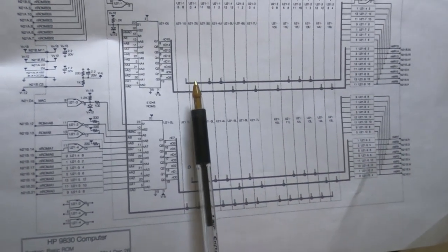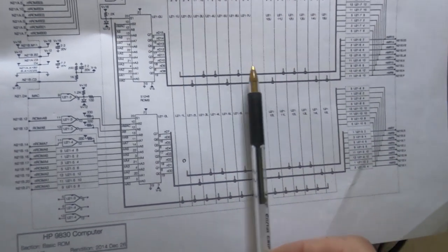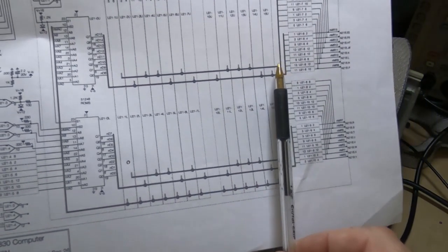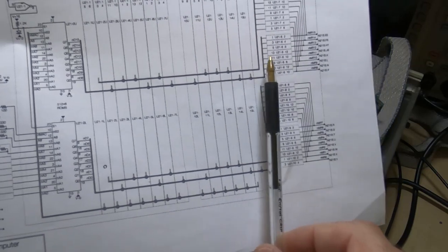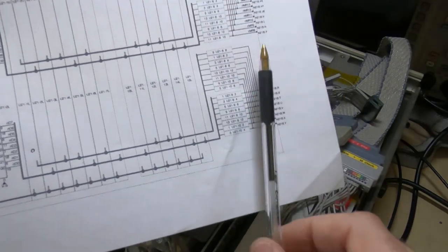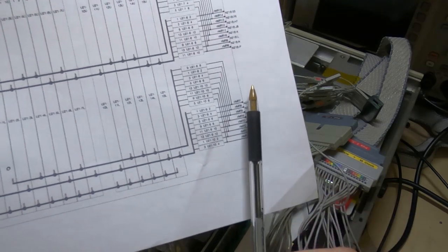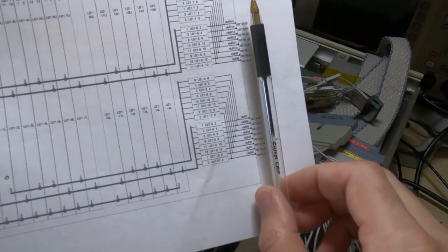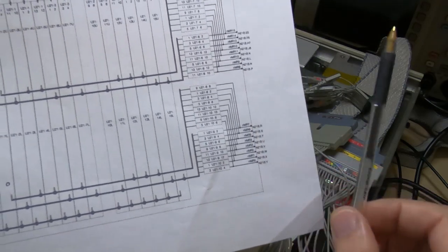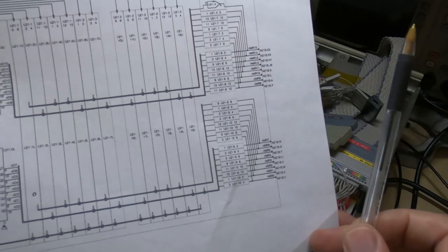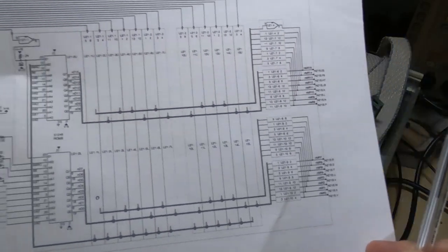There are some strange things going on even within this, because all the outputs are hooked together in 2 banks, and then they're combined on the output of the output buffers, and then from here they go to the T register, and the T register is responsible for reading the 16 bits together, and then it can feed those 16 bits into the CPU in a serial form.